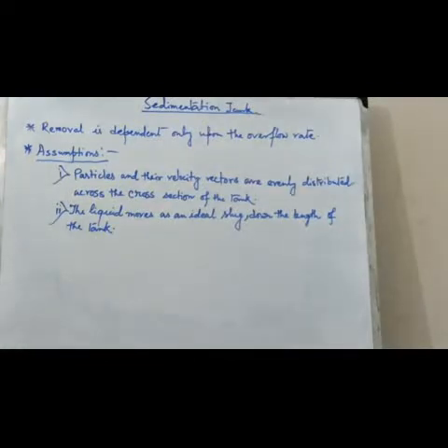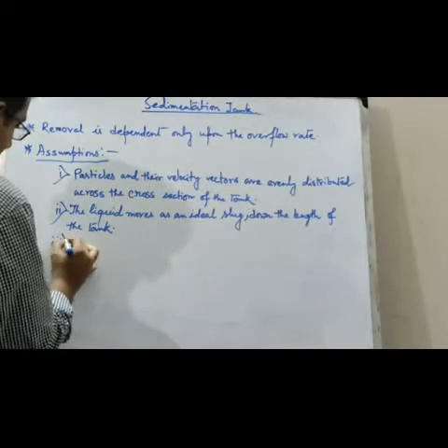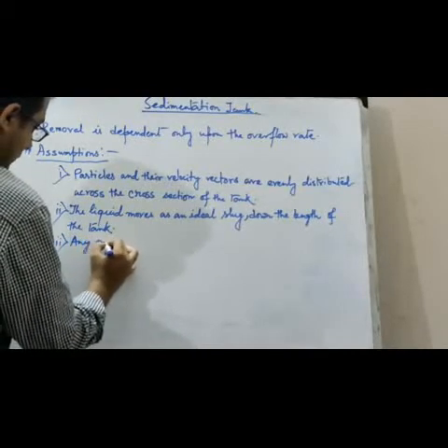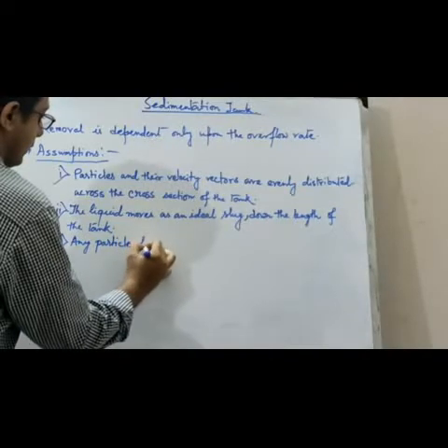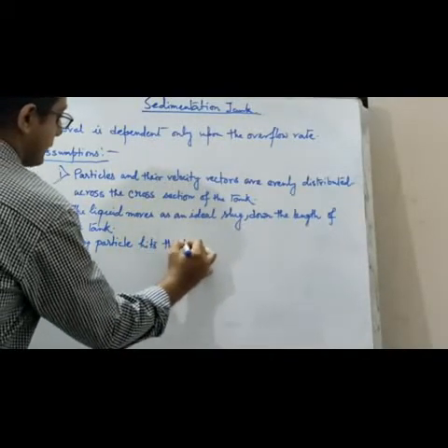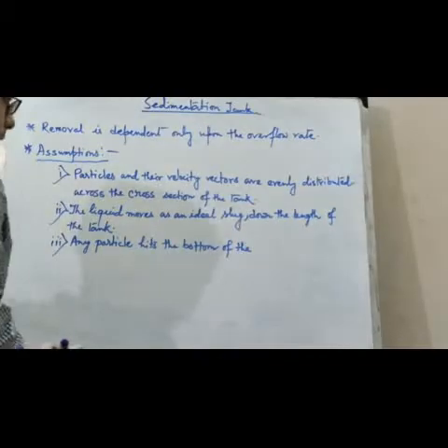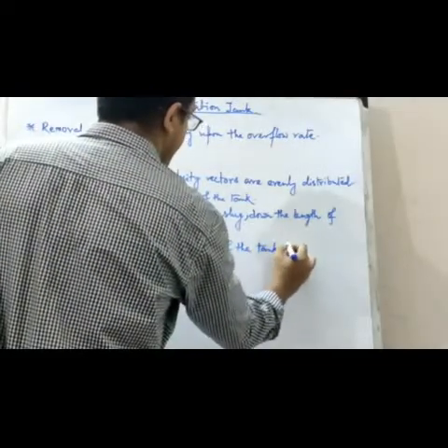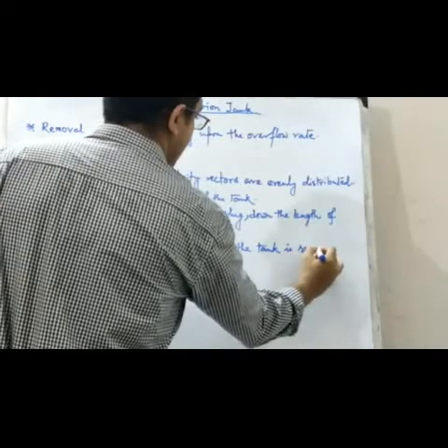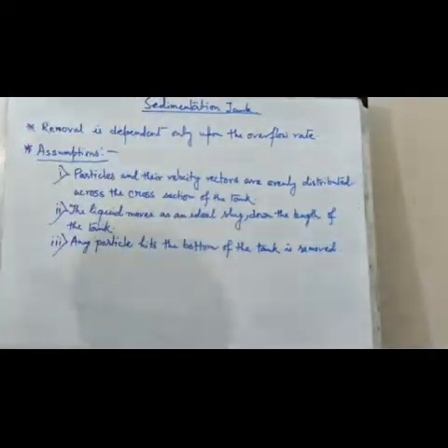And the third thing is any particle hitting the bottom of the tank is removed. So any particle that hits the bottom of the tank is removed. These are the main three assumptions of sedimentation tank.